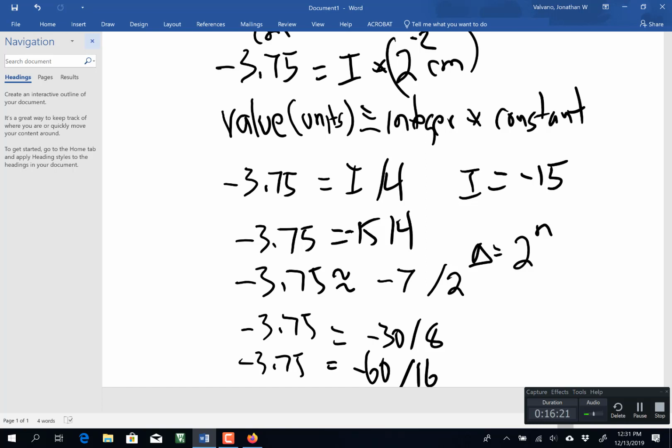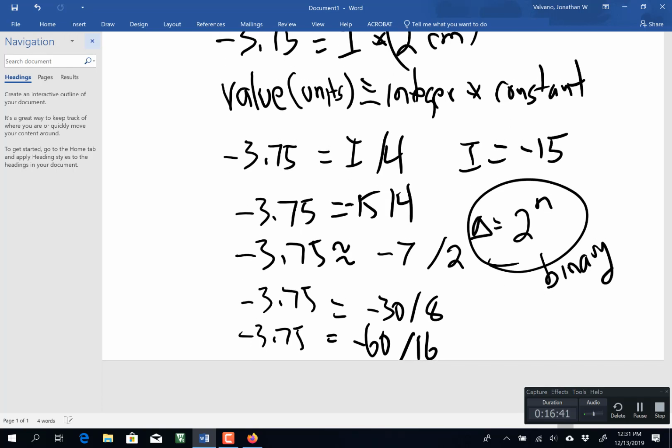Yeah. So from a design standpoint, I'm going to choose a power of 2 such that I can represent the values that I need. To answer your question, would it always be a power of 2? Well, a binary fixed point is always a power of 2. Okay. What is a decimal fixed point?